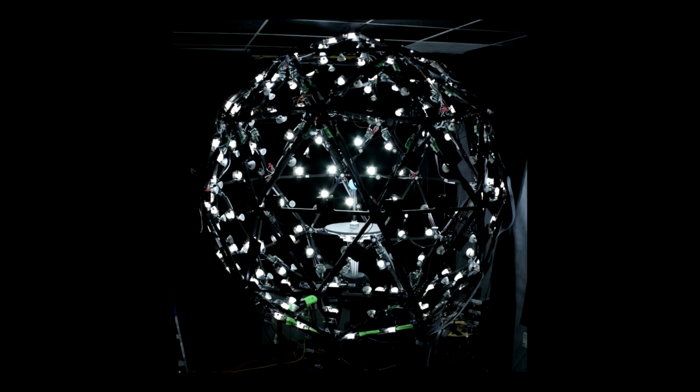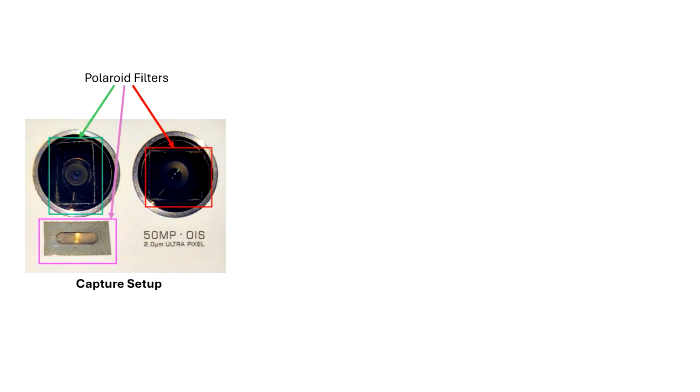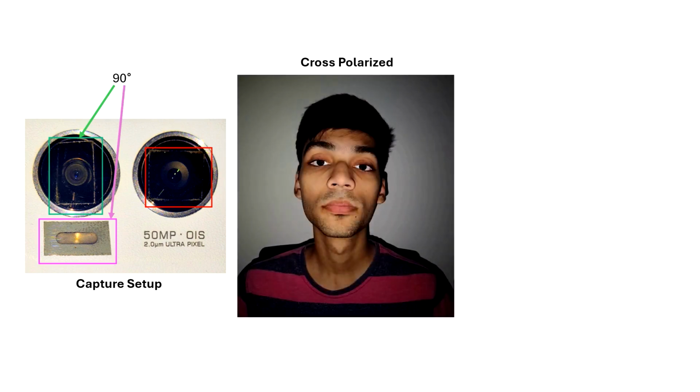One of the key components of a Lightstage are the cameras equipped with parallel-polarized and cross-polarized filter arrangements to independently capture the illumination information in the decomposed form. Leveraging the same principle, we place a thin polarized film over the flashlight and two back cameras of a smartphone, one at a relative angle difference of 90 degrees with the flashlight's polarization angle to capture the cross-polarized video stream, while the other at 0 degree relative angle difference to capture the parallel-polarized video stream.